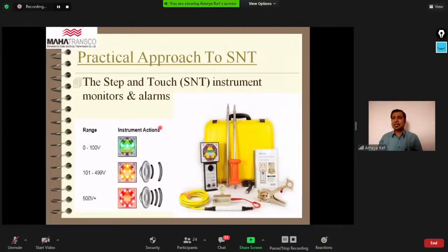There is a reason. Now we have a good network available. Each transmission line, distribution line, HT line, EHV line, and UHV line crosses each other, so there is good potential sharing between these lines in terms of interference and induction. And because of cogeneration lines also, there is good interference in the network. So we are not able to identify whether a particular tower is properly earthed or not. I am highlighting this only for the case of emergency.